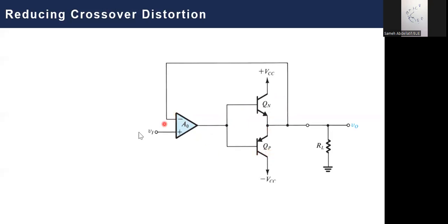Similar will happen when this input is negative 0.1, it will be multiplied by 5, then it will be negative 0.5, and then this will turn on and this off. What will happen here is, assuming that we have a 5 gain unit here, that you minimize your dead band from being from negative 0.5 to 0.5 to be from negative 0.1 to 0.1. So you still have a dead band, but this dead band has been limited or reduced somehow.